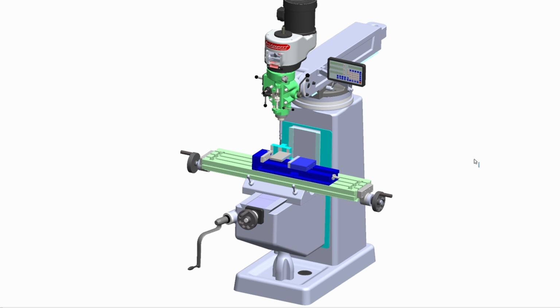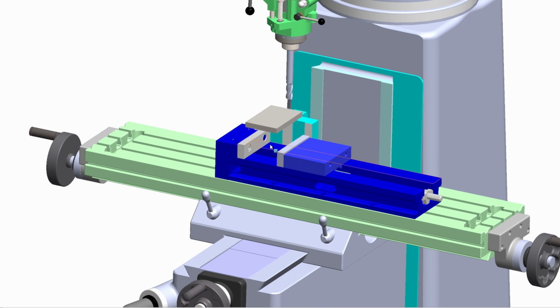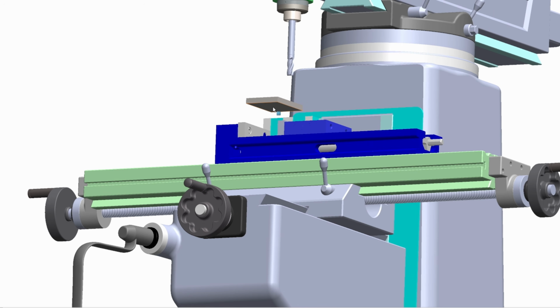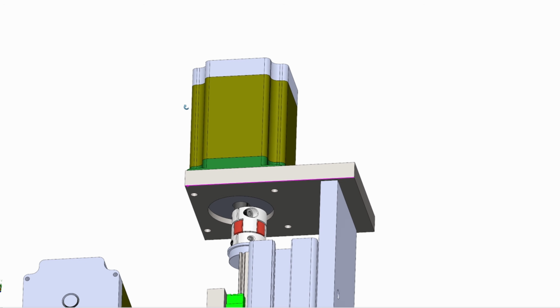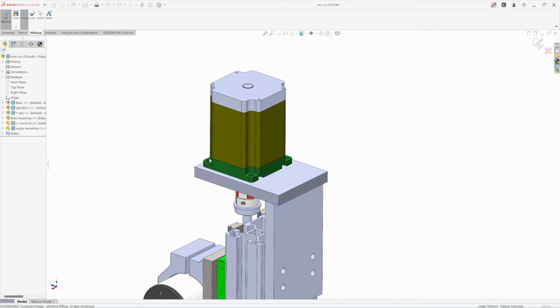And this one is the first design intent of this part: how the part is to be set up, how the part is to rest, and the resting plane of the part for the manufacturing and the inspection, as well as in the assembly. And we define this setup intent with datums like datum A, B, or C, which we will apply later in this video. And now back to the assembly.